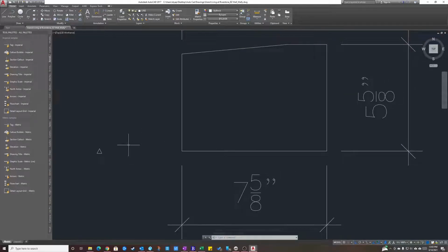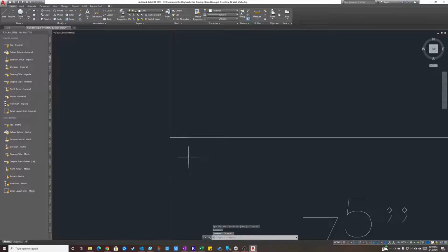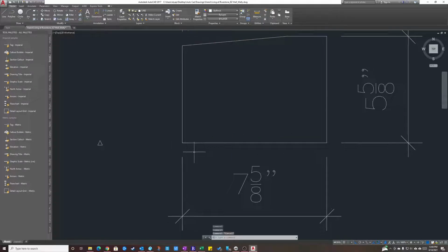Whoop-dee. What do we do with that triangle? All right, grab your line tool, click on the front edge of that stone, drag your cursor in the direction you want to draw that line. We want to draw that line 3/8 of an inch long. So you type in 3/8, enter. What does that do? That gives you a line overlapping the other line. You see it right there, because that's the line we just drew. It's 3/8 of an inch. And this is the line that we already had, which is the stone. So what are we doing here?